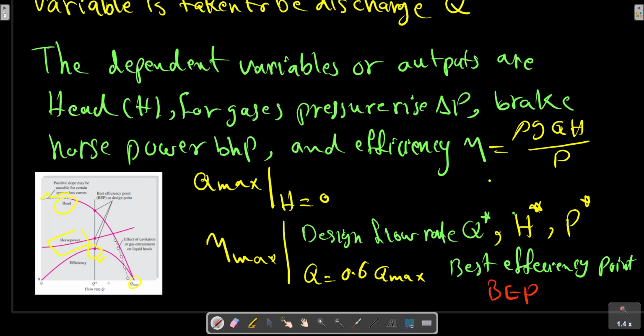This is considered undesirable because a much larger motor is then needed to provide a high flow rate. Backward-curved blades typically have their horsepower level off above BEP, a non-overloading top of curve. Other measures of performance curves we'll discuss in the next video part.